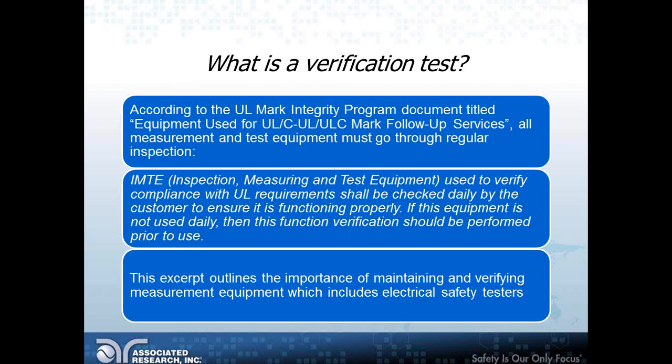So as a result, these damaged units can give incorrect readings with regards to the insulation resistance or the leakage current. Therefore, performing regular verification on electrical safety testing equipment ensures that the unit, the tester itself, is operating properly, and you are testing to the NRTL standards.